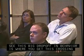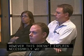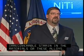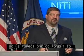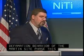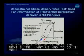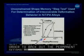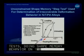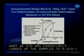However, this doesn't explain necessarily why you get this irrecoverable strain in these alloys. And so we forgot one component to this, and that would be the permanent deformation behavior of the martensite phase. And this is a little bit harder to back out. If we have the next slide, what we had to do in order to back out the permanent deformation of the martensite is go through and do these step tests doing shape memory behavior on the material. So what we did was essentially load up the samples to a given strain, unload to say 0.3.